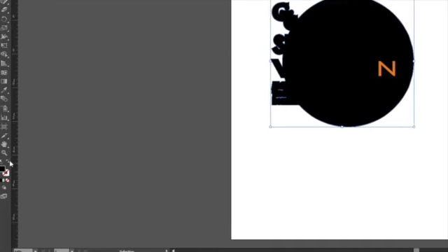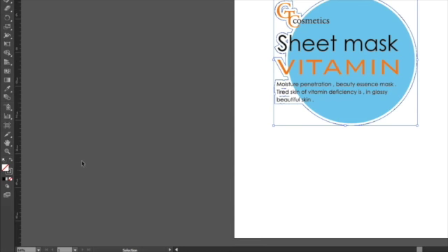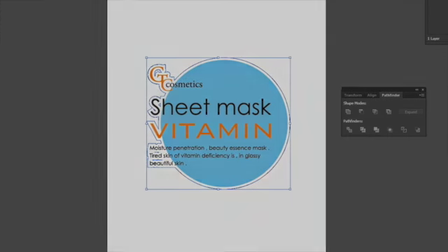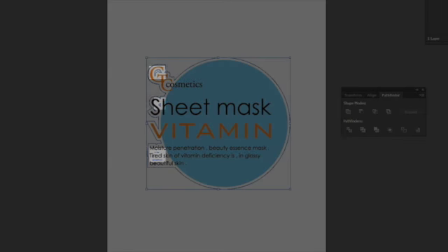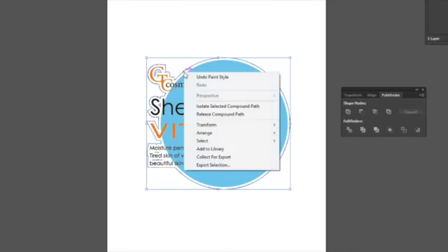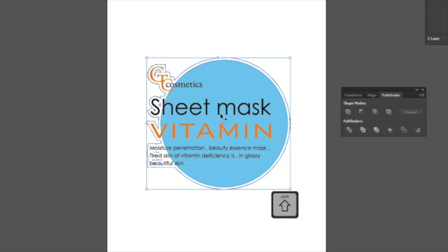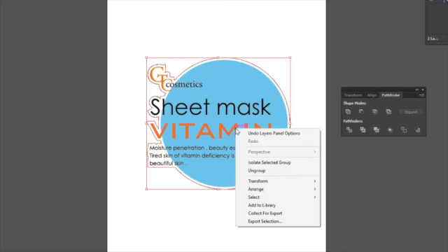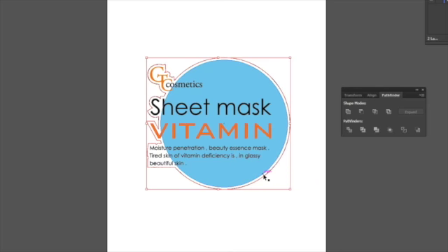From here, let's make sure the cut path has no fill and there's a stroke line. If you need to remove the holes inside the new outline, first release the compound. Hold the Shift key and click on the outline. Delete the smaller object inside by pressing the Delete key. And finally, ungroup it.